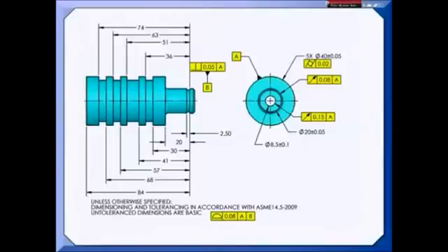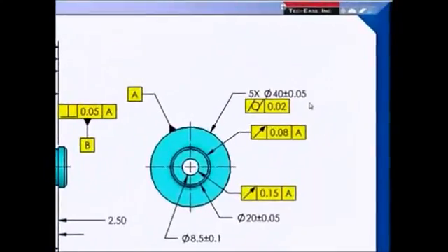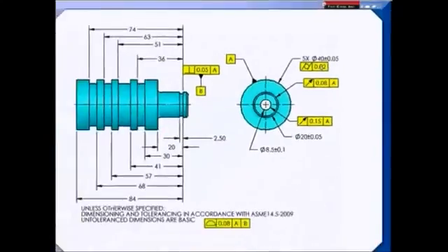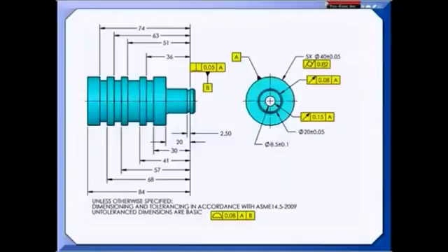Usually in assemblies, we like to have interchangeability of parts, but that's not always the case. In some hydraulic and pneumatic applications where you want a metal-on-metal seal, the parts are selectively assembled. In other words, they're matched. Let's say that this is a spool for a spool valve in one of those applications. I would make up several spools and try to keep them very cylindrical while I allowed the size to vary. Notice that the size tolerance is bigger than the cylindricity tolerance by quite a bit. Then I would grade the spools, match them up to bores, and do a pressure test to make sure that they're not going to leak.